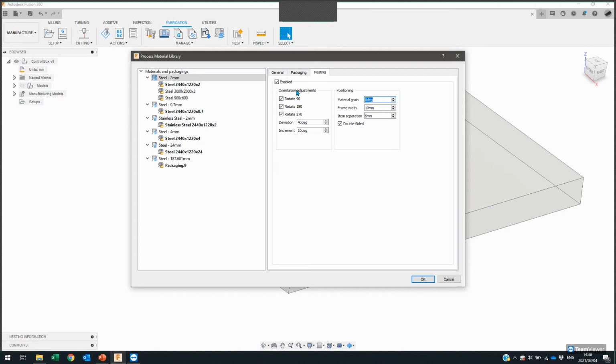We have other orientation options. Are you allowed to rotate components on the sheet by a set angle? So this would just control how the algorithm rotates and moves and turns that component to fit into the sheet. You know, like your Tetris. Tetris, you can only rotate to 90, 180, and 270 degrees, and your original 0 degrees.